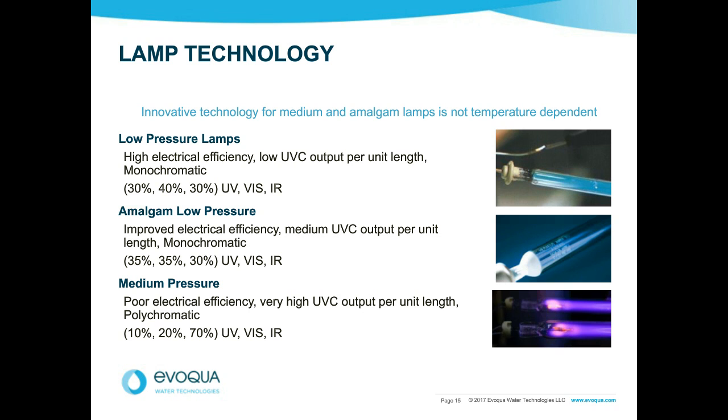It needs to have enough lamps. It needs to have effective wipers. That's very important. We put an access hatch on the wastewater machines so operators can get their hands into the reactors and remove algae or debris that could foul a clarifier. It's very hard. You can't take an ultra pure water machine and expect it to work in wastewater. You have to design it properly. It's a different geometry, different type of lamp, more lamps. But if you understand that, it's a very successful application. And we have many excellent case study quality and reference grade installations.